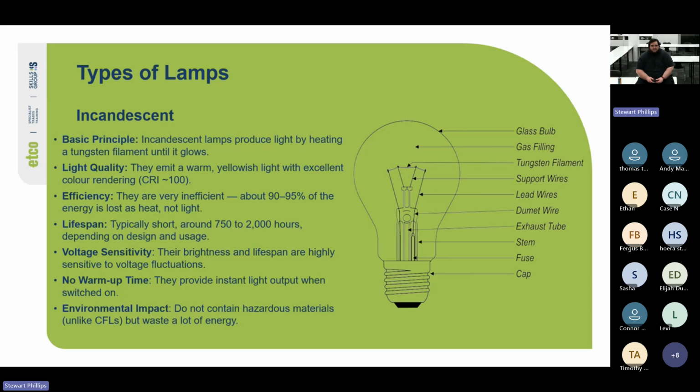But yeah, always make sure you pay attention to the polarity of Edison screw light fittings. Bayonet cap does not matter because both the pins are inside and you push the light bulb in and twist.